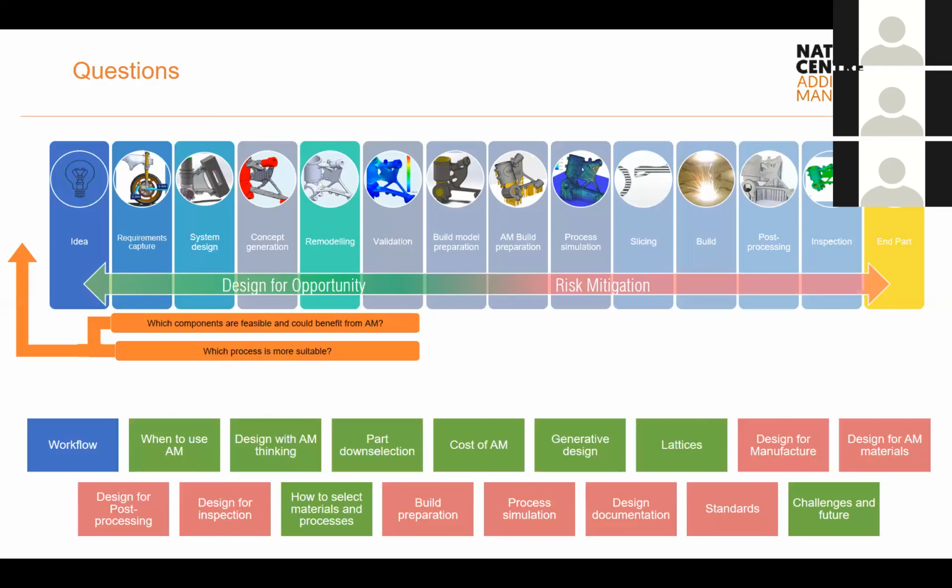Then what you get is repetition of the same part with the same conditions, even fixing the same machine. So you validate one machine, and the one next to it is not validated until you make sure that it's producing the same parts. That's how it is being approached specifically on the powder bed fusion technologies.